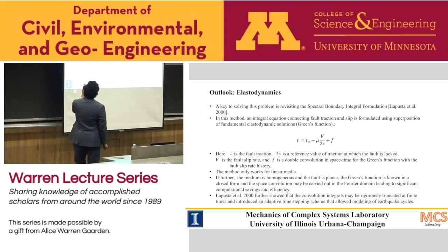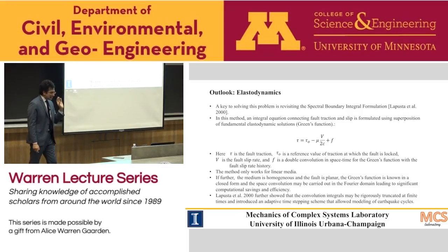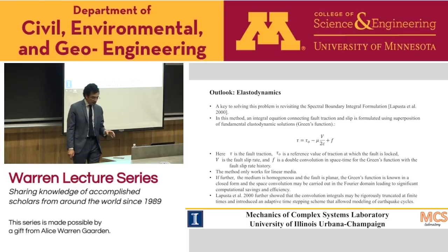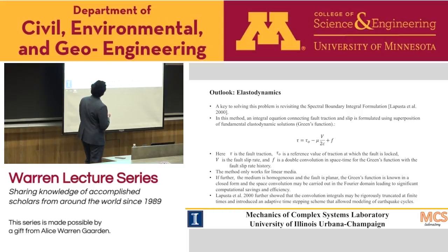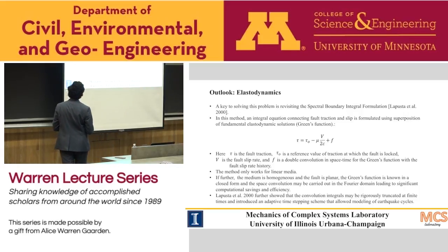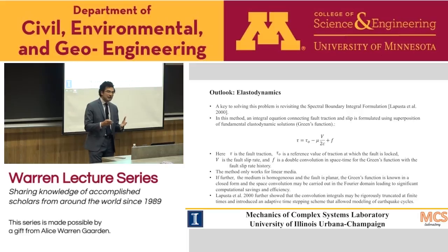So there is a very interesting method that was developed by James Rice and Philippe Guibel called the spectral boundary integral formulation, and it was actually expanded significantly by Nadia Lapusta and Jim Rice in 2000 to allow simulation of long-time sequence of earthquakes. And the method is built on the idea that if you have a linear elastic bulk, then you can use superposition of fundamental solutions.